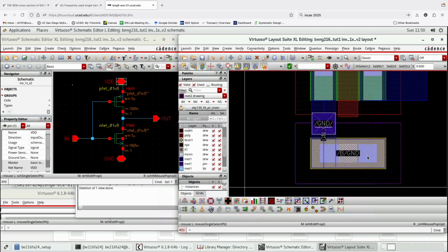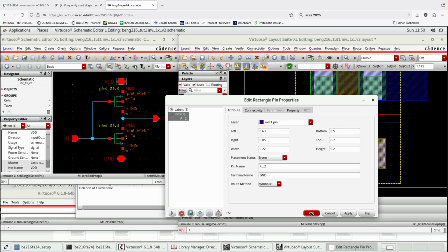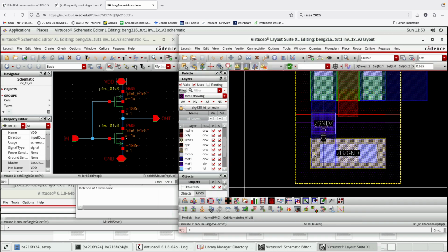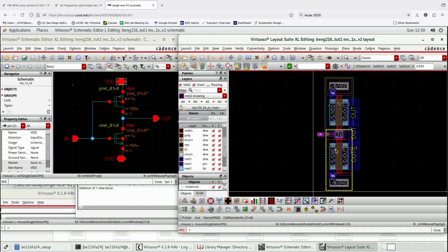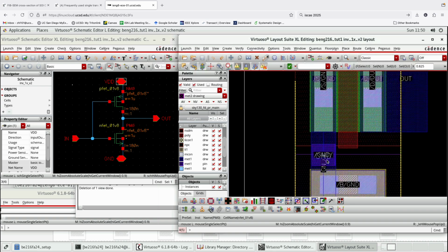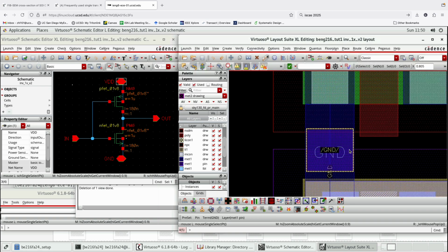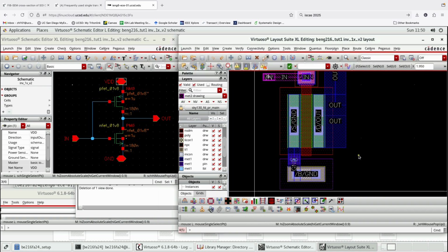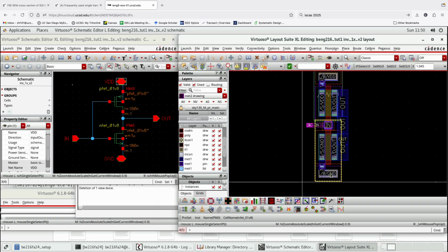And this is also, again, a beauty of having your layout and schematic symmetric, right? So you can just copy everything. It's going to make your life easier. And you see there are no markings. The previous marking disappeared, which is good. Okay, and I bet that previous marking was a shorting marking. Right? It detects that we're shorting ground to VDD because we put the VDD pin over a ground as well.